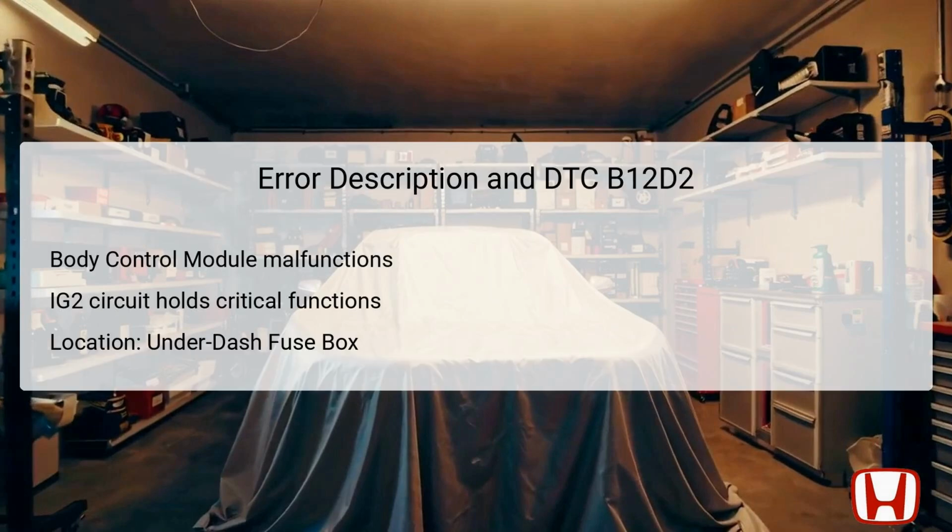The DTC B12D2 signifies a malfunction in the power control unit's IG2 circuit, which is crucial for powering various electronic systems in the vehicle. Essential to the operation of the vehicle, the body control module, BCM, manages these power distribution tasks. The BCM will store this DTC if it detects that the actual state of the IG2 circuit differs from what it expects based on input signals.